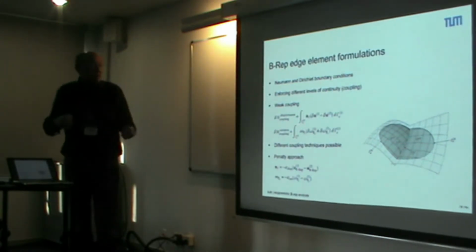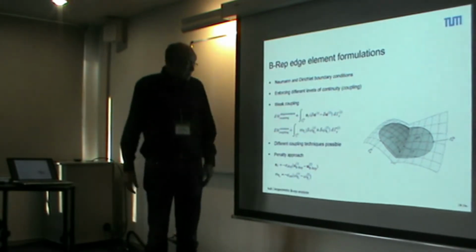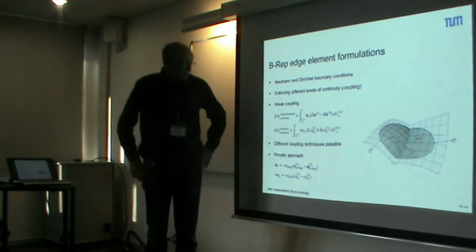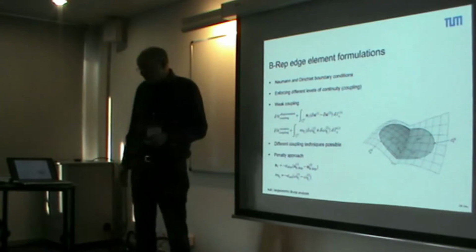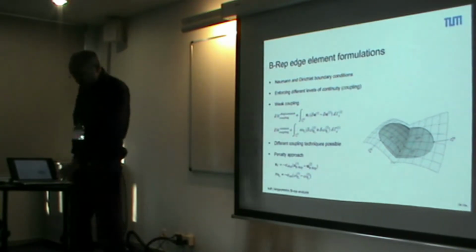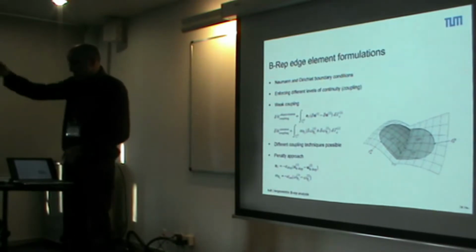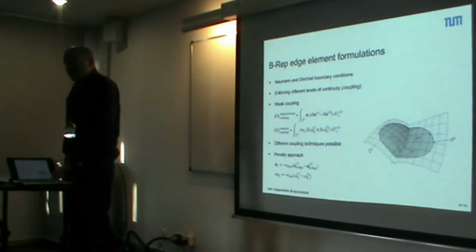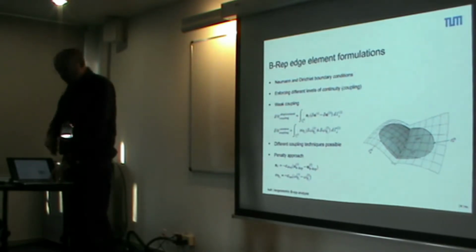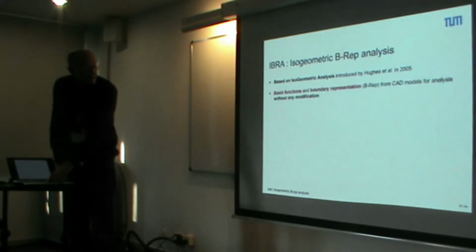On this edge element, of course, you're just formulating these boundary conditions, perhaps in terms of this penalty approach, which appears to be quite nice for all kinds of applications, including, of course, implicit dynamics. From our experience, I agree with you, we don't need more than penalty formulations. They can be used for many kinds of applications.